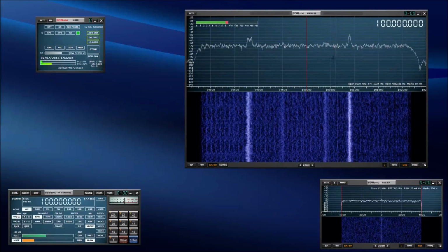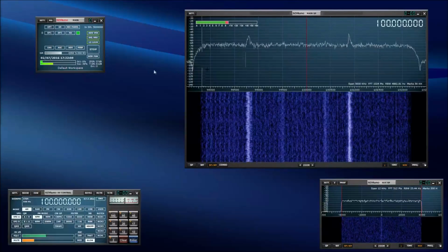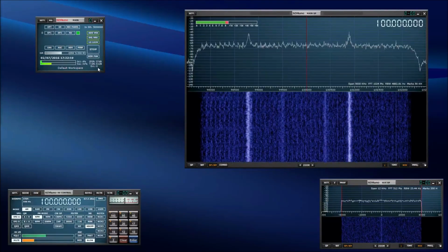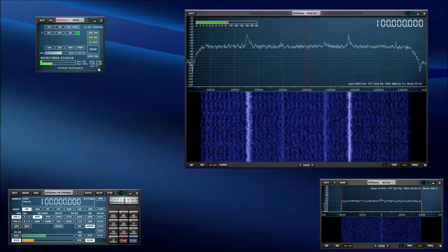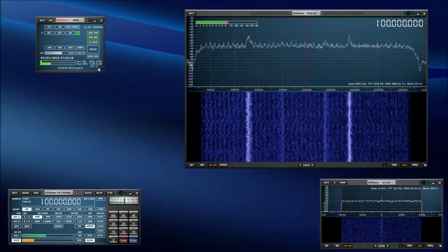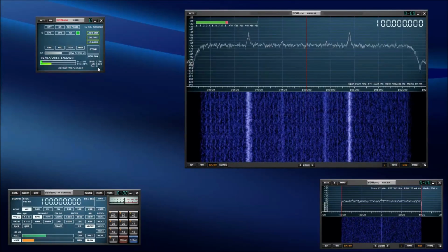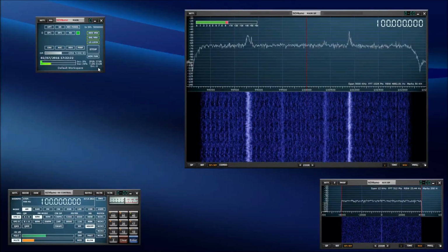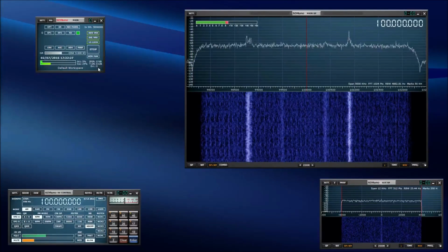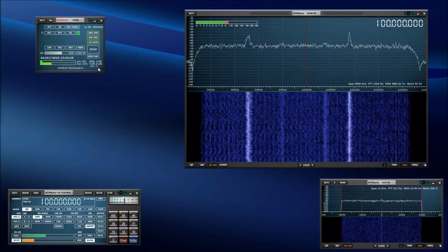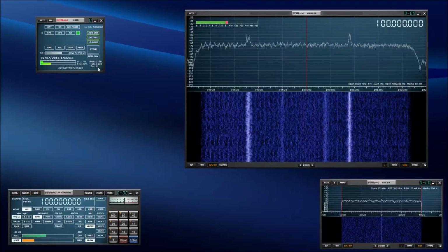So that's why the noise. I know somebody commented the other day that they were turning the LNA on and off, but the noise floor isn't changing. Well, we did it the other way round to start with. When you turned off the LNA, we had that amount of gain reduction coming off the entire total system gain. And what people were saying was, hey, I've got my LNA on, and I'm using AGC to get near, and then I turn the LNA off, and my whole noise floor drops by 24 dB.